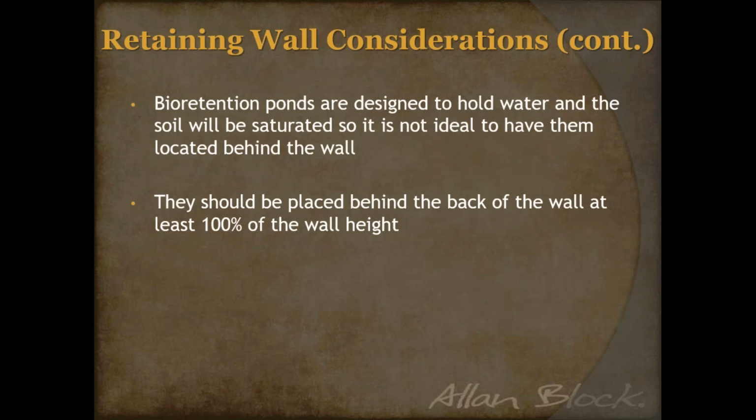But I do want to talk a little bit more about this water and location. Since we know bioretention ponds could potentially have that standing water, by all means, we know they're going to have saturated soils behind this wall. Anybody that is familiar with the retaining wall designs, and I know there's a bunch of you on this call and this webinar that have some experience, you should start kind of twitching a little bit when you start talking about handling saturated soils behind a segmental retaining wall. That is one of the biggest do not do's in our industry.